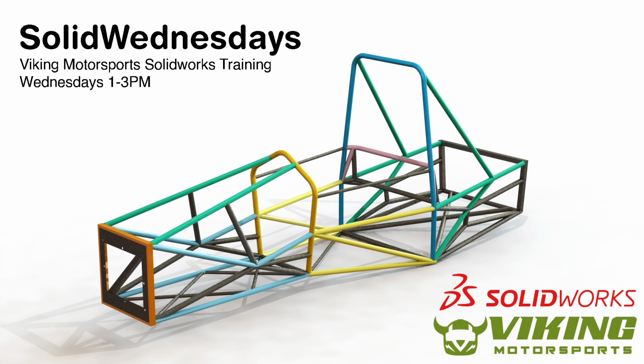Weldments is basically how we design what looks like what we see on the screen there, the frame of the car. Key things with weldments to remember is that you're going to have a constant cross section for whatever you're doing. So all these tubes, they're all defined by their outer diameter, or if it's a square tube or a rectangular tube, the length of the width, certain thickness, and all along that tube it's going to be that same constant cross section. Because we design a lot of these same kinds of parts, instead of having to extrude a lot of stuff and shell and all that kind of stuff, SolidWorks created weldments to make it easier for us to create these complex structures.